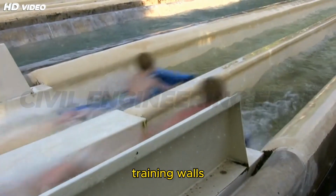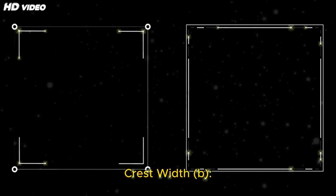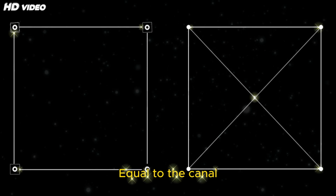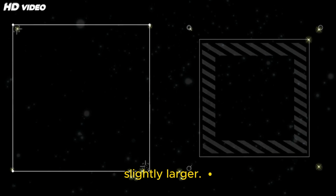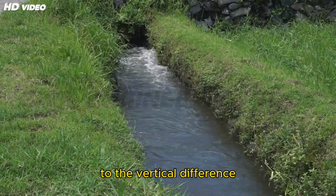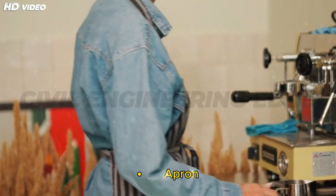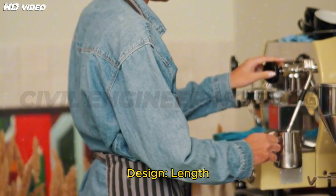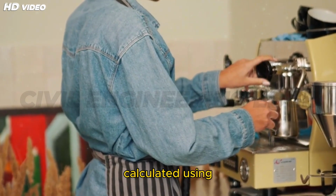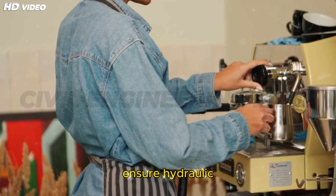Side walls and training walls ensure flow stability. Design parameters: crest width B equal to the canal bed width or slightly larger. Height of drop H equal to the vertical difference between upstream and downstream canal beds. Apron design: length of apron is calculated using empirical formulas to ensure hydraulic jump formation. L equals 5 times D2.